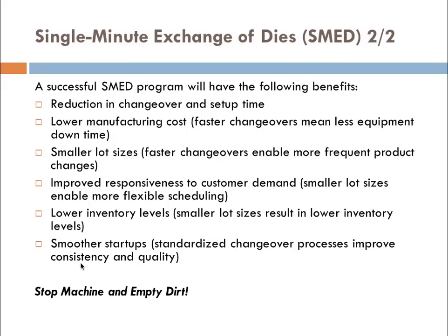Therefore, a successful single-minute exchange of dies program will have the following benefits: reduction in changeover and setup time, lowered manufacturing cost because of less equipment downtime, smaller lot sizes because of more frequent product changes, improved responsiveness to customer demand, lower inventory levels, and smoother startups. Now, the easy way to remember the single minute exchange of dies, SMED, is also by saying stop machine and empty the dirt. Stop machine and empty dirt.